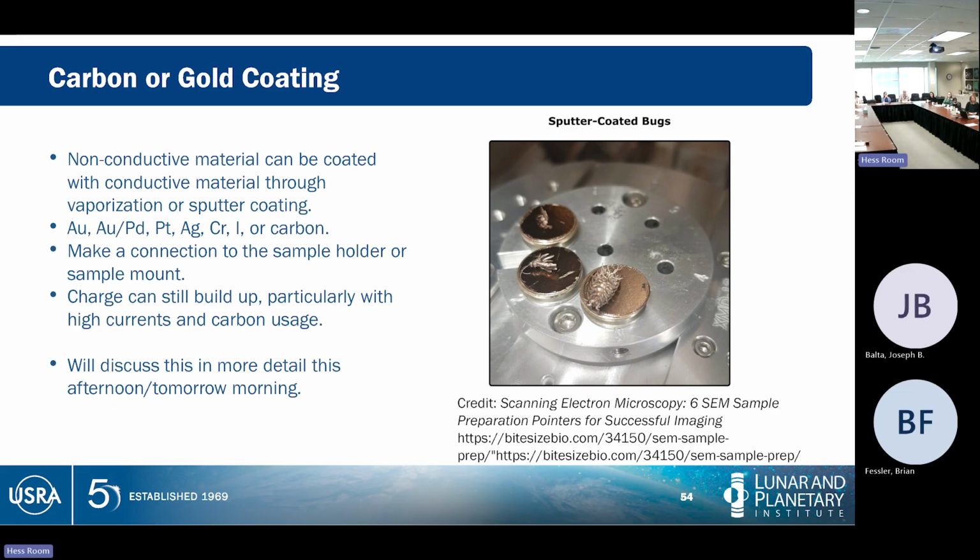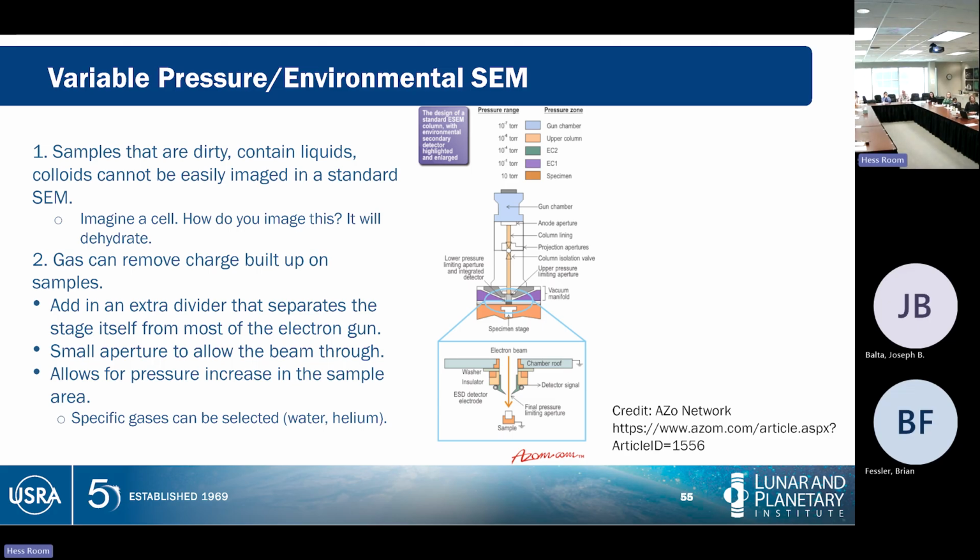If you make this nice electrical connection between your sample holder and your sample, charge can get removed. It's never perfect. You have to maintain things sometimes. If you're at a high enough current, you may still get some charging around there. You know, if you crank your microprobe current up, you can get charging even on a coated sample. We will talk more about this and actually practice this with carbon coating on geologic samples later.